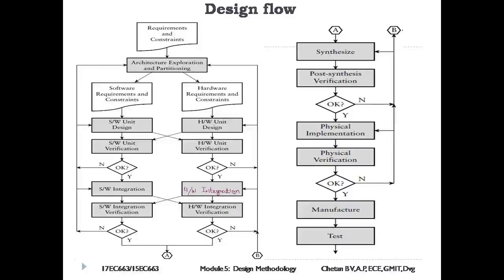Design flow. Design methodology is not standardized across the industry. Each organization defines its own design methodology based on the kinds of design projects it undertakes and evolves the methodology from project to project. A prototypical design methodology divides the design flow into a number of stages, that is functional design, synthesis and physical design. Each stage includes verification steps to ensure that the design meets its requirements and satisfies constraints.